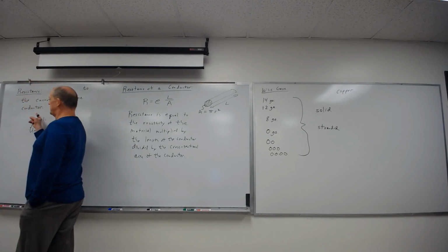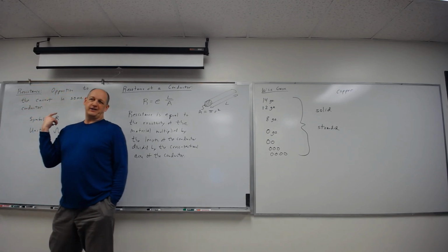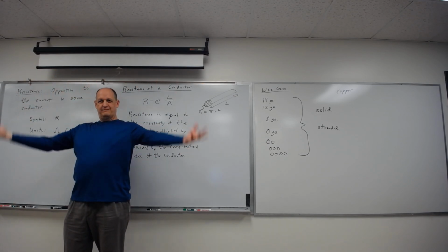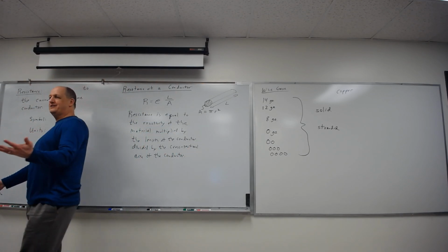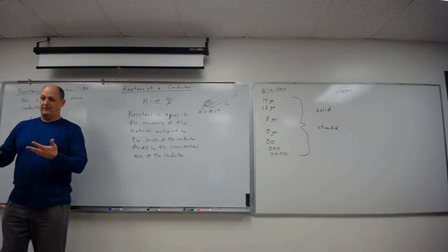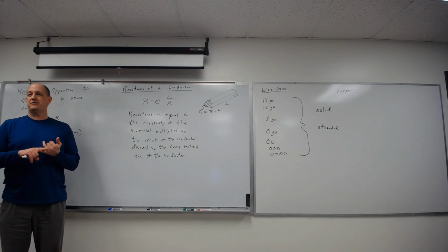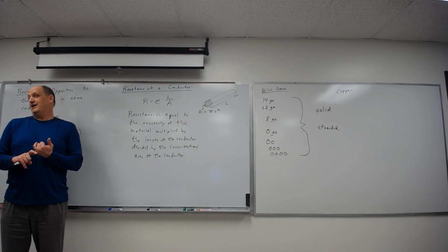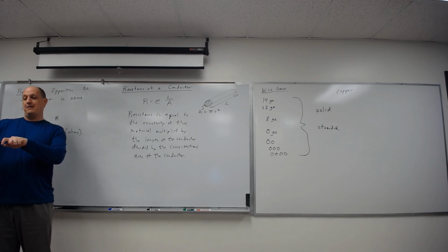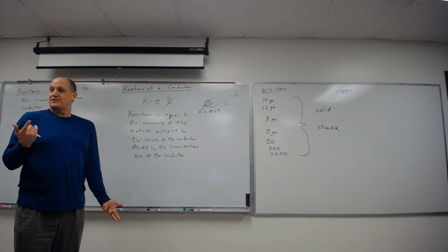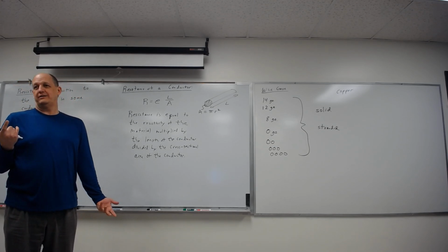What are all my conductors going to be? What conductors can you think of off the top of your head? Silver. Metals. Yeah, iron conducts just fine. Silver conducts very well. Silver conducts better than copper. So why don't I do household wiring in silver? It's expensive, it's frail. Yeah, it's expensive. It's also frail. Silver, I can just grab a wire, boom, oh, it broke. Copper is strong. Steel is stronger. Why don't I use steel wiring?